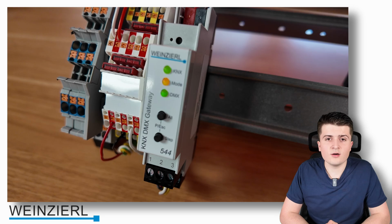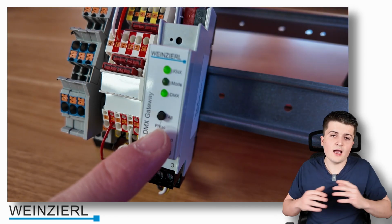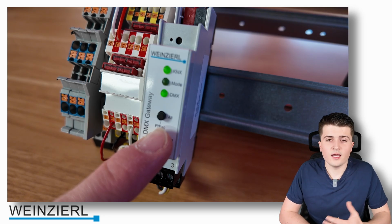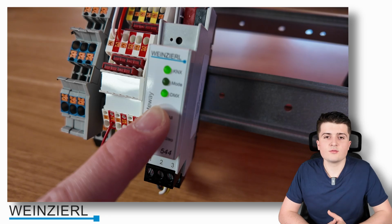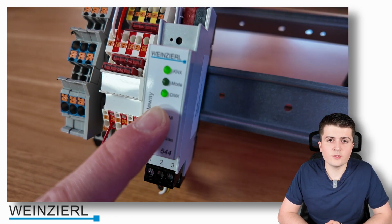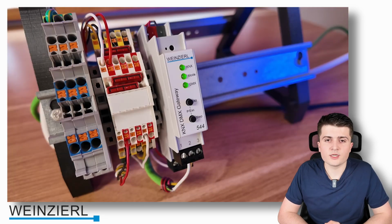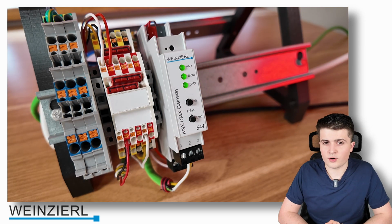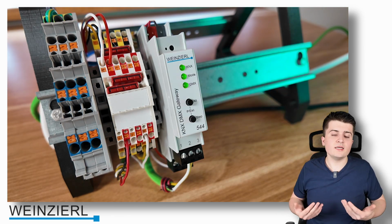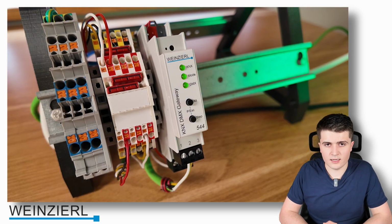So with that we are now in manual control, and send broadcast telegrams, so to every address on the DMX device. And now those two buttons can be used like for typical dimming in KNX. That means with a short button press on the upper button, we turn every address to 100%. With a short button press on the lower button to 0%. And with long button presses on the upper or the lower button, we can dim the addresses up or down. And so with that, we can easily see if all connected DMX lights react to those telegrams.